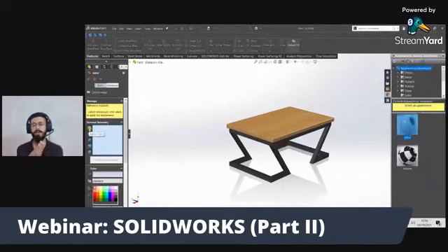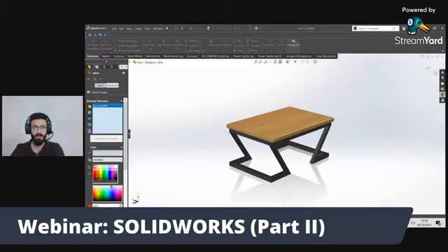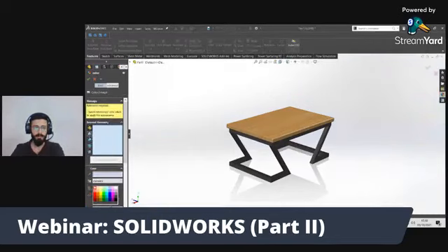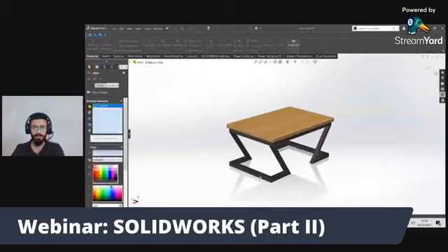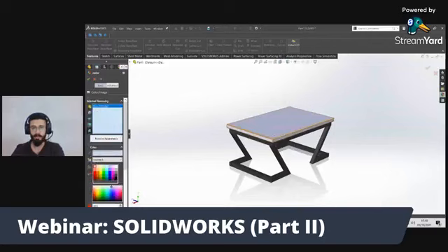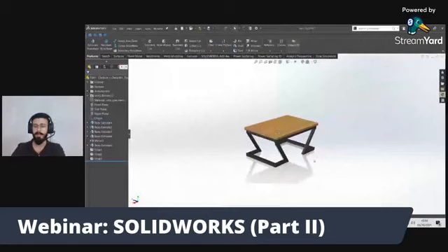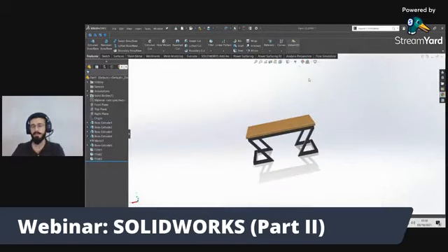If you just want to add a color to just one face, there is the option of face, a surface, there is the option of a complete body, there is the option of feature. Like this is some extrude cut. Okay, this is an extrude cut. Here I will go to feature. This is my extrude. It will just select that extrude. It will just select the next boss. See, boss extrude. It will just select the boss extrude, but I will not add it. This is how we use appearance on our model.